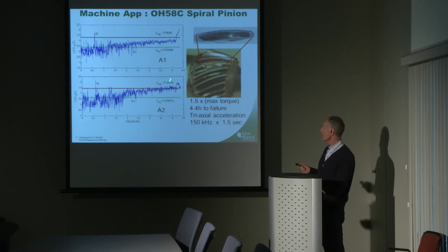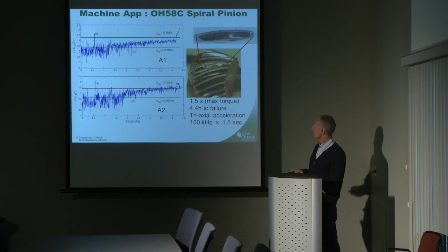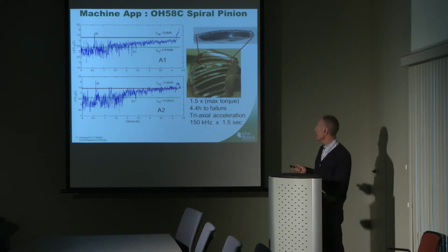The data here were acceleration data, and what one finds is that there is a threshold above which the dissimilarity measure rises and stays above that. And this is the forewarning region. And then there is a second threshold. When the dissimilarity measure rises above that level, that's an indication of the failure onset.